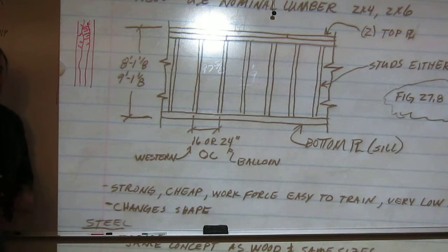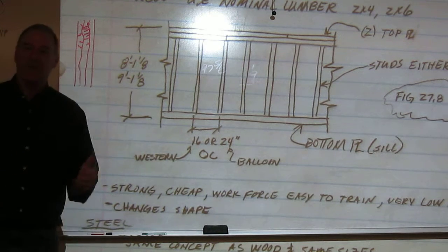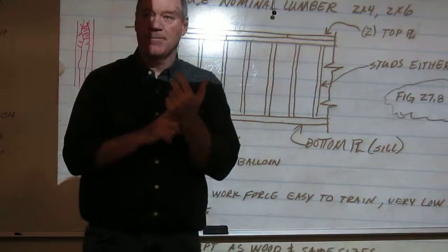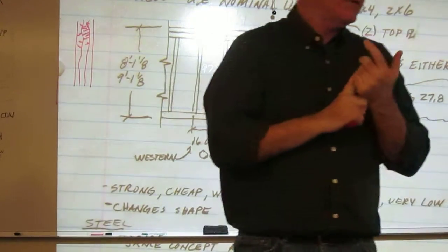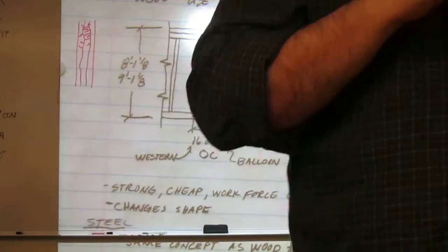The spacing of our studs, you can go four different real spacings that we use here. We use 12 inches on center, 19.2 inches on center, 16 or 24.